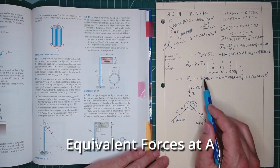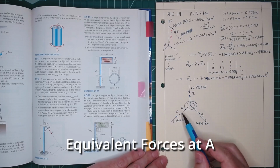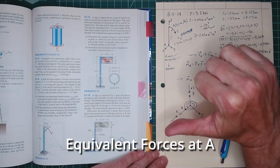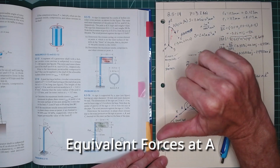We needed the rotational forces or the moments. So now we can look at these guys here. So, moment about point A in the I direction. Now remember, that's in the X direction. We have a negative 7.496. Now if we look at this, remember we use our right hand rule. So our x-axis is positive in this direction, so we put our hand there.